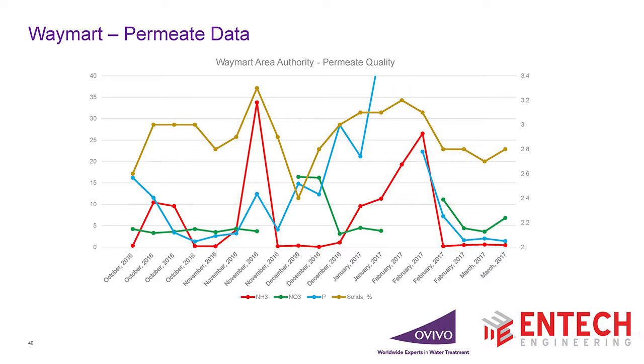Most of those adjustments had to do with not having quite enough dissolved oxygen, not enough aeration. Also, the brown line indicates the thickness. We tend to note that if we try and get it much above 3%, we lose our digestion because we're not getting the oxygen transferred.